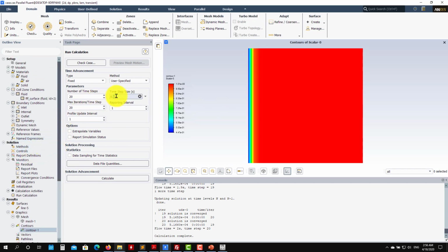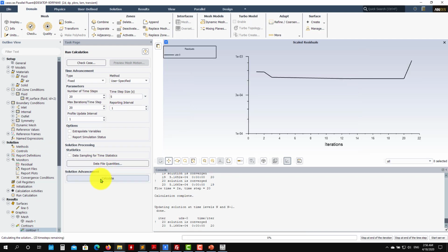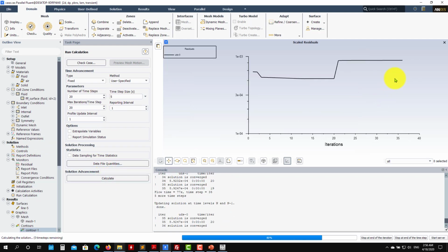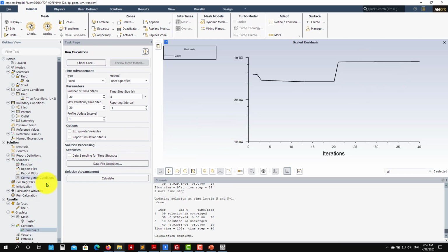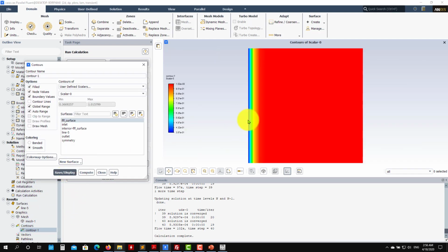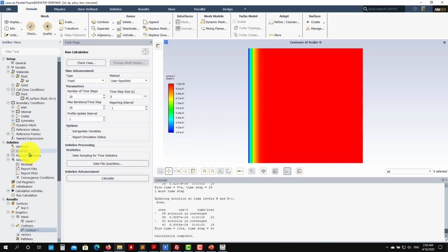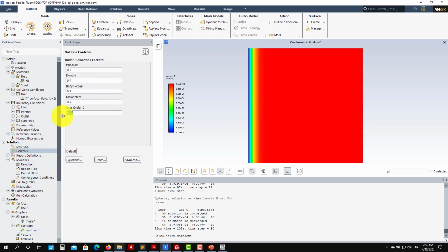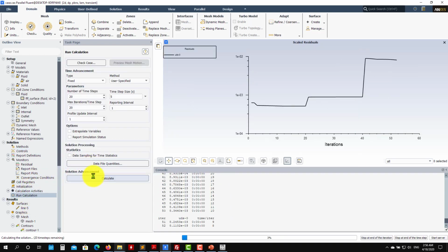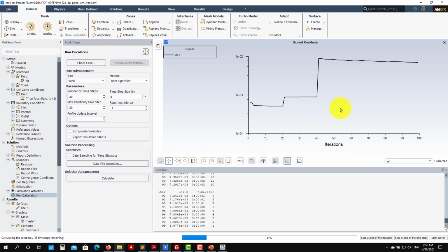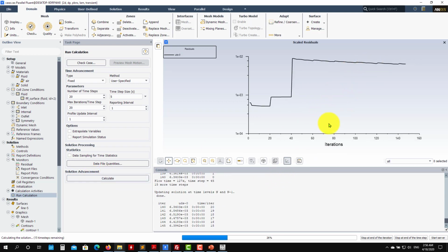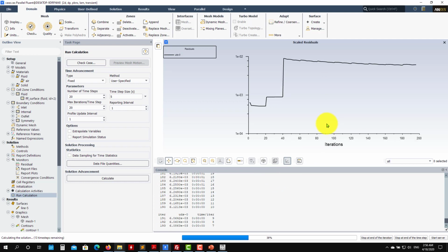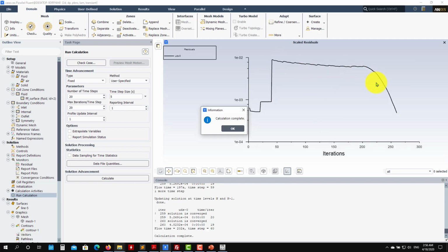So even if I go here and put a time step instead of 5, let's see what happened with the solution. Okay, the propagation is still very slow. So if we put it to 0.1, this value should go fast. Okay, see that now it's converging slowly. But here you also have the influence of the time step, which is very large, and now it's going down.